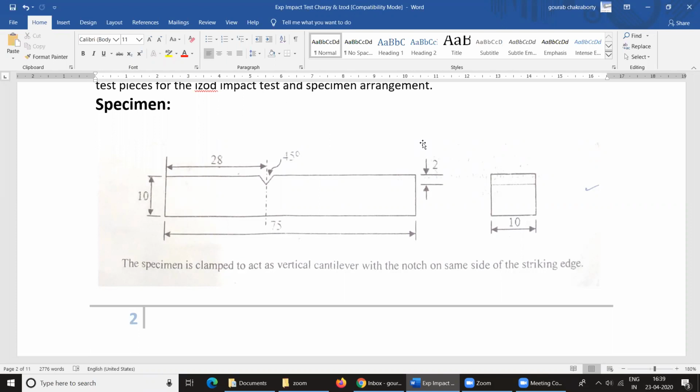The loads are usually applied slowly so that the test piece may be considered to be in equilibrium with the load at all times. Such static tests do not predict the behavior of the material when parts are subjected to rapidly changing or reversing stresses and to sudden stress and shock.